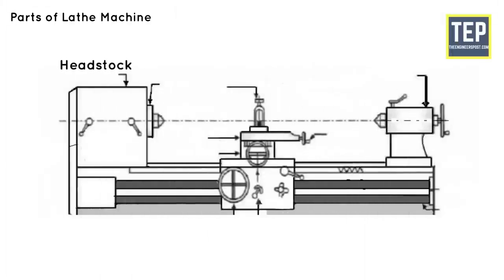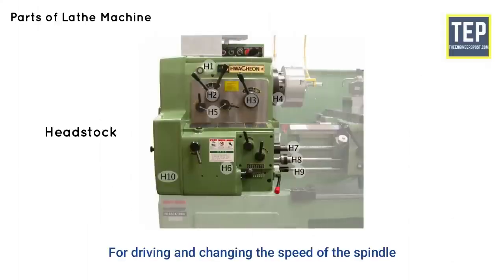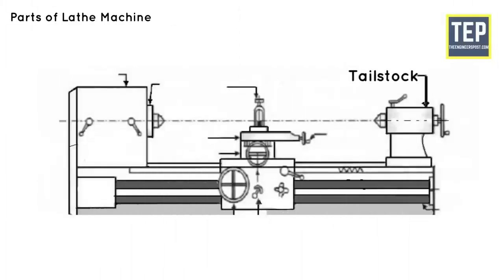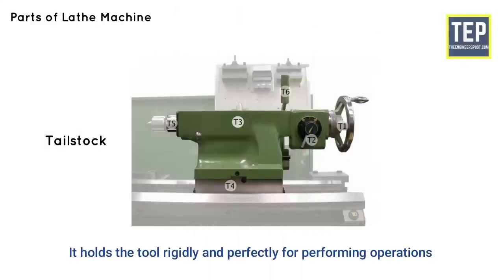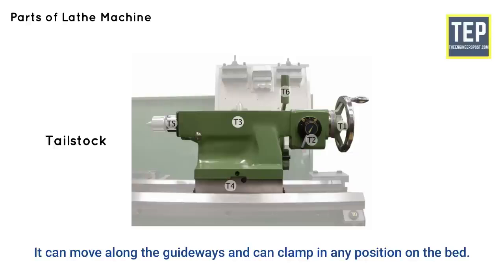The headstock is located on the left-hand side of the lathe bed. It has a hollow spindle and different types of mechanisms for driving and changing the speed of the spindle. The tailstock is located on the right-hand side of the lathe bed. The tailstock supports the other end of the workpiece when it is machined between two centers. It holds the tool rigidly and perfectly for performing operations, and it can move along the guideways and be clamped in any position on the bed.